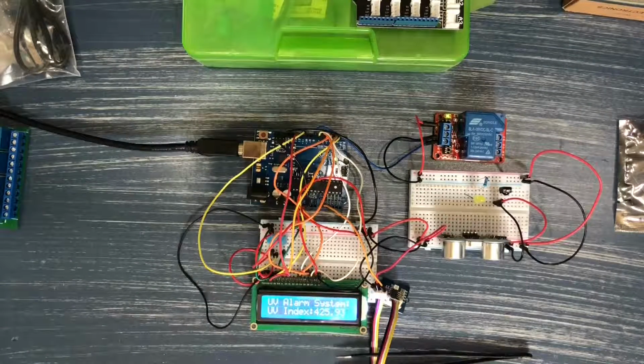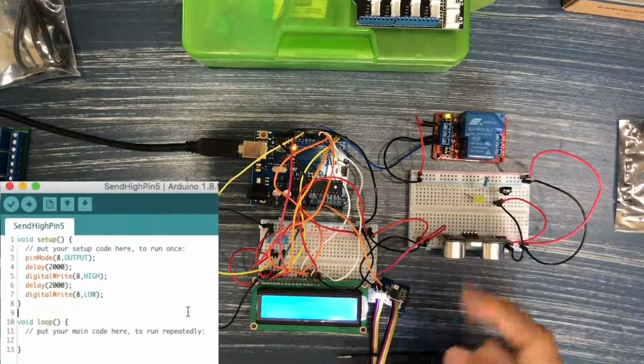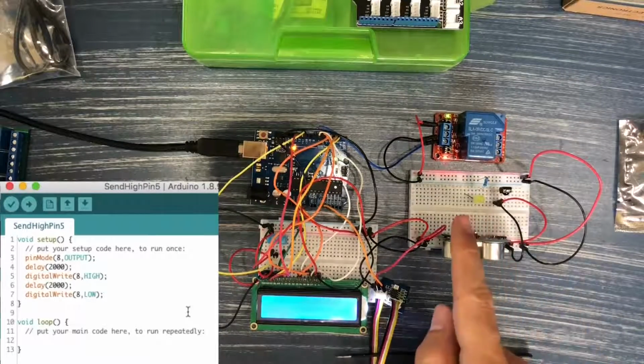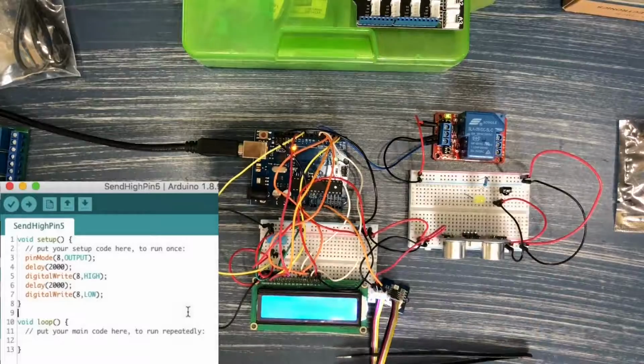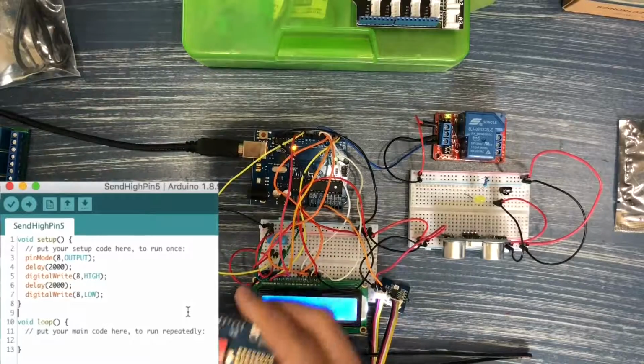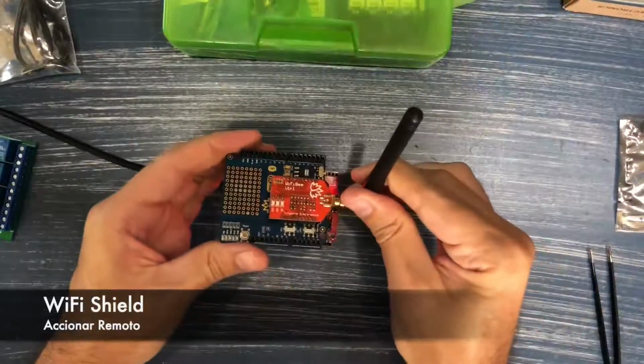Okay, so here is the code for the relay, and as always it is down in the description of the video, and I'm uploading the code right now, and you see the LED there, it's on, and then it's off. Okay, and I only put it in once, which means I put that code in the setup function. Otherwise the relay would just be going on and off continuously, and of course it's not that exciting if it's not connected to anything, but that is basically what the relay does. All we do is we send a digital write high to the pin we are interested in, and then a digital write low.